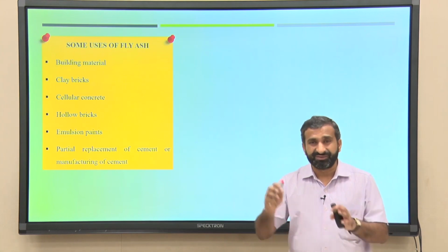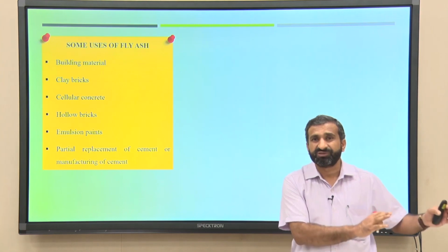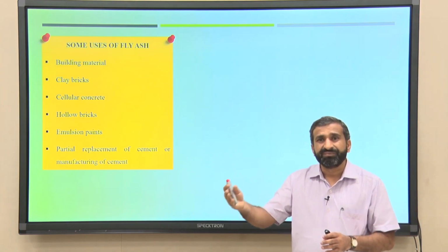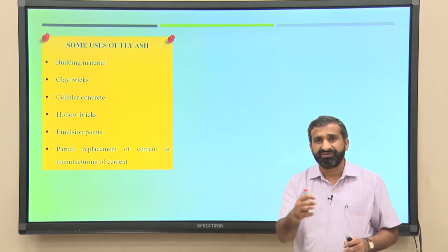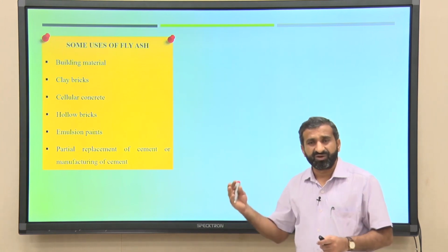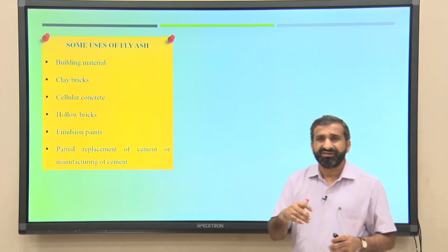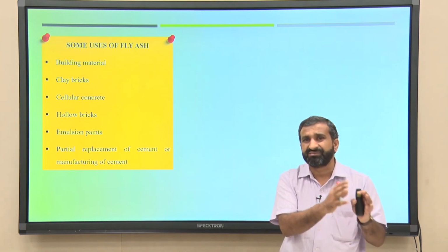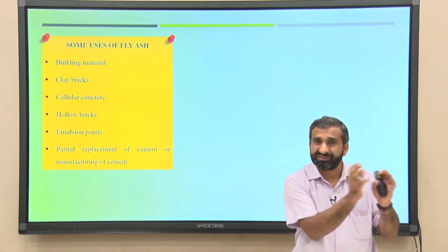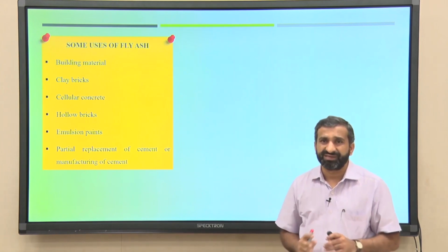So, in that case it was always proposed that whatever fly ash is produced in the coal power stations, that ash could be added to prepare the fired brick, maybe 5%, 10%. If you add it, their compressive strength should be more than whatever the standards available. And why these kinds of ashes are beneficial, because they also contain calcium, they also contain silica, which is also required to increase the strength of the material.